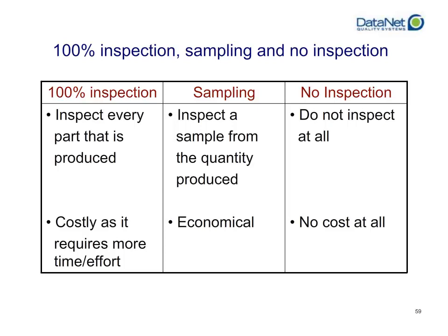The advantage to 100% inspection is that you literally inspect every part that you produce, and you have a handle on everything that's left the factory. If you have a good database system where you can track all that, it's not a big deal to retrieve that information if you ever have a customer complaint, and you can prove that this was either a good or not good part. You can correct any issues that occur as they happen.